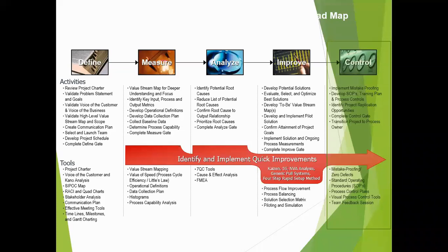You remember we identified repeatability and reproducibility. Same part number, same equipment, same operator doing it multiple times will give us repeatability. Multiple operators measuring the same part will give reproducibility.